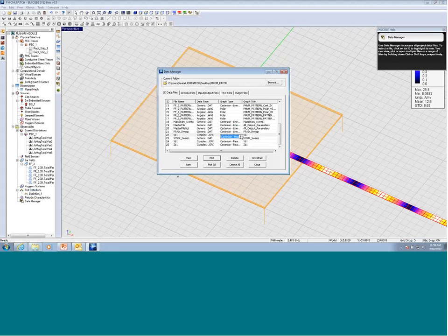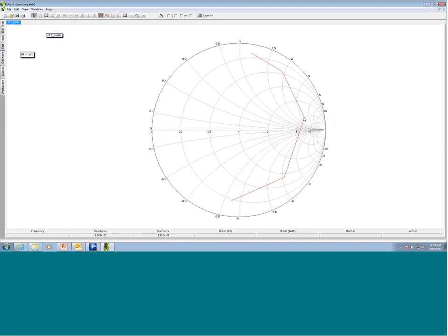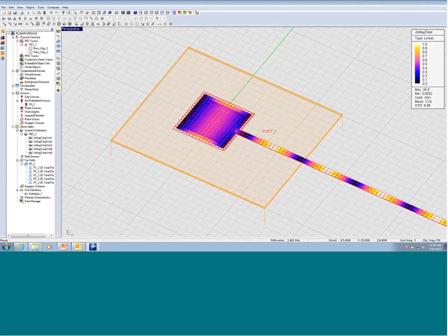Another thing that we can do is look at the S parameter as a Smith chart. And again, as you can see, somewhere here, this is 36, 37, 38. I'm cutting the real line, which means that my reactance goes from positive to negative. So these are some design tools that we can use for tuning the antennas.